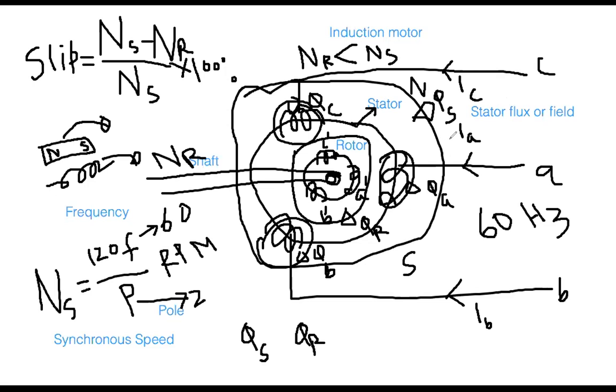This was the main driving force, this stator magnetic field. And that caused the voltage here and consequently another set of flux. That's why naturally the rotor speed is lower than this one. Now it might happen that you could make this speed much bigger than this one. For example, I said, you see this condition, NR less than NS. If you make, for example, by force, NR greater than NS, for example, you make this situation.